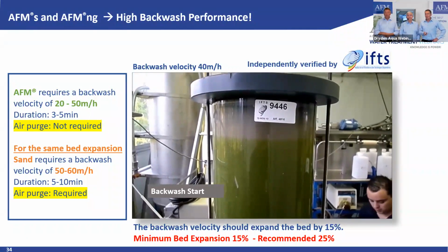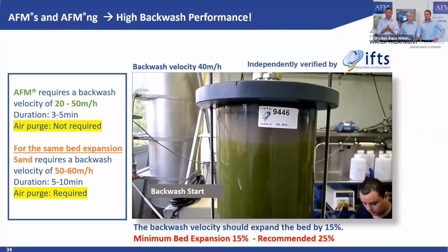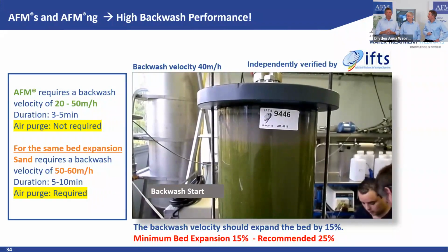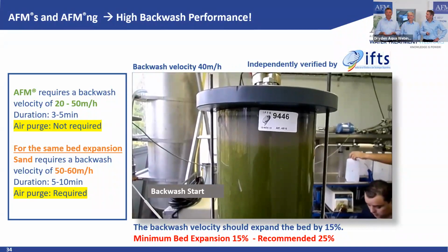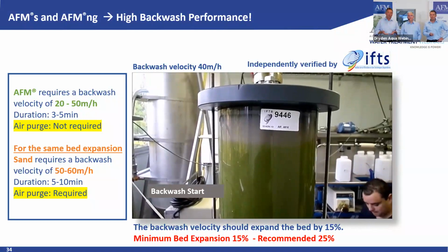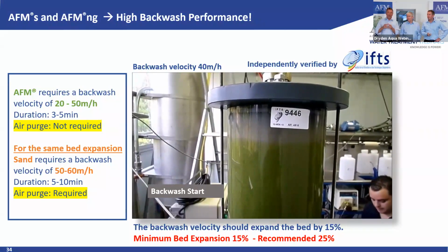And that was a big surprise for me. You were, and you still are, of course, the heroes, your water treatment people. But in one thing, I was really surprised, in a way, about backwash velocities. I mean, in pools, it's clear that we backwash our pools at 50, 60 meters per hour because we have these side glasses.